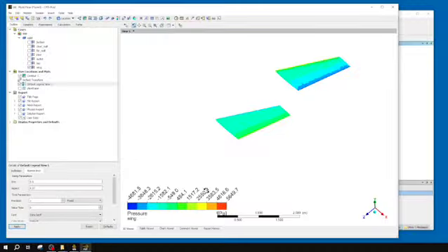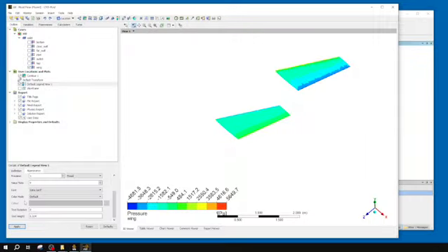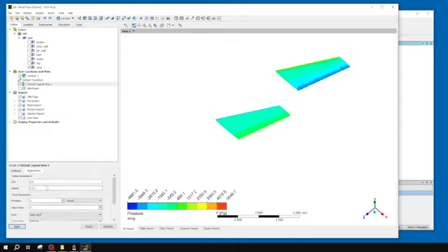And I think the text is a little big, so instead of a 2.4, I'm going to just do 0.2. That'll shrink down that text a little bit, and I don't want it interrupting this bottom bracket, so I'm going to change the size down to, let's go 4. Let's see what that looks like. 4 is good.